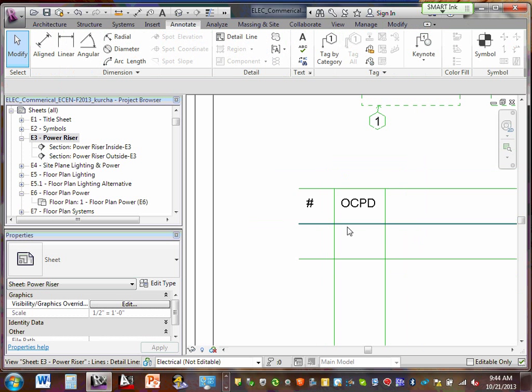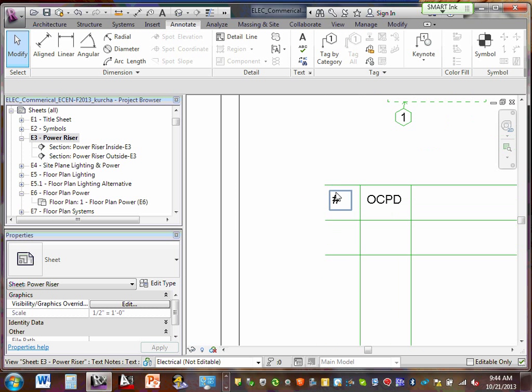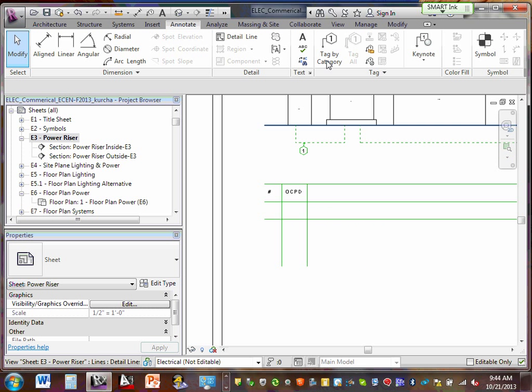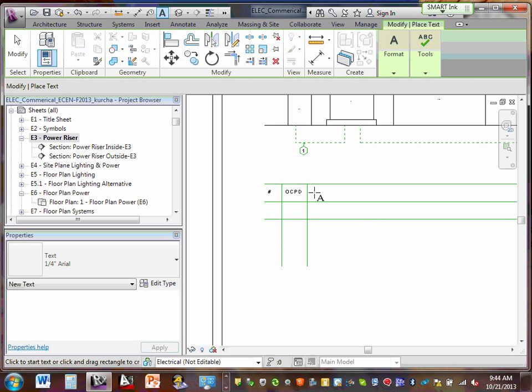You need an overcurrent protection device, and you need feeder size. Feel free, guys, feeder size. That should be the title of your equipment. Then you come over here and you put, this will be your number 1. This will be your feeder is 500 amp.